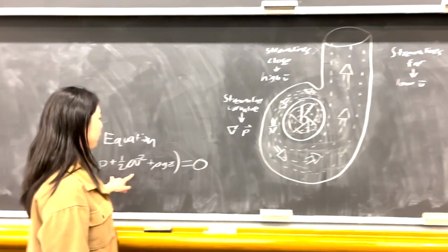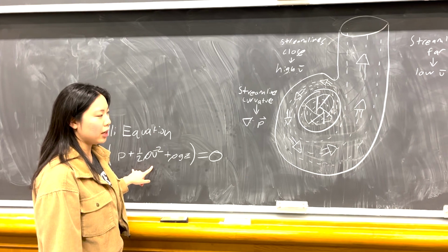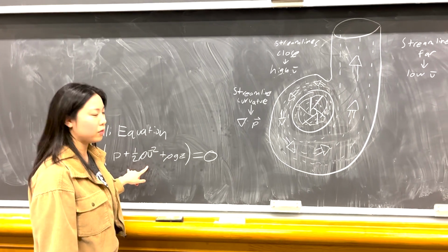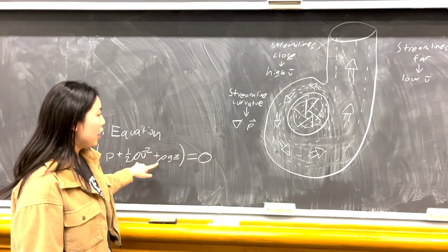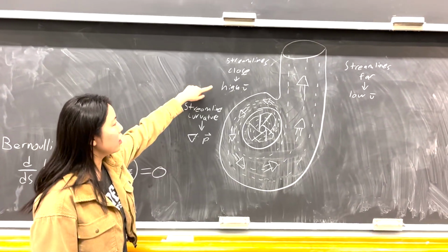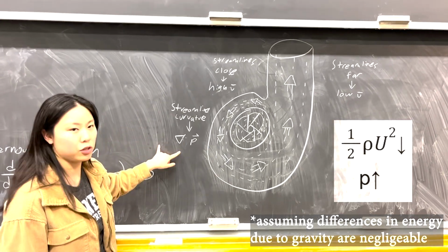So we can use Bernoulli's equation, since the energy in the fluid doesn't increase after it leaves the impeller and we assume inviscid flow. We can say that the Bernoulli constant stays the same through the volute, and we can use the Bernoulli equation to say that since the speed of the fluid decreases as it goes through the volute, the pressure increases.